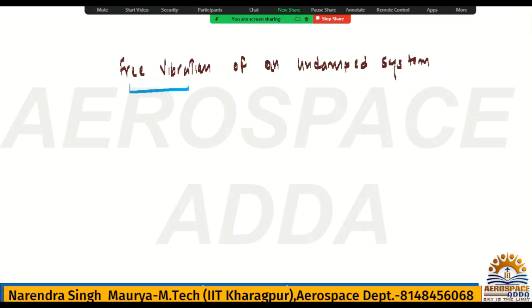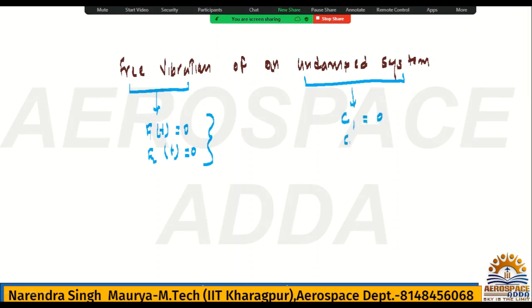If they said free vibration, that means the forces F1 and F2 both will be 0. So this is sorted now. And now they have said undamped system. So undamped system means what? That means damping coefficient C1 will be 0, C2 will be 0, C3 will be 0, all three, because it becomes an undamped system. Undamped means damping is disregarded, yes or no? Damping is disregarded, so obviously it becomes an undamped system.